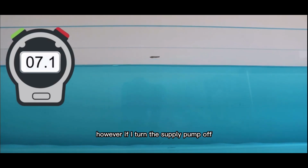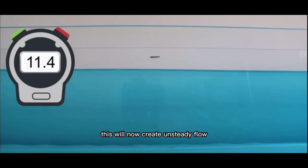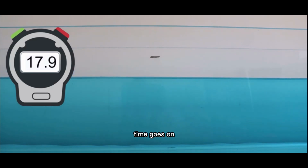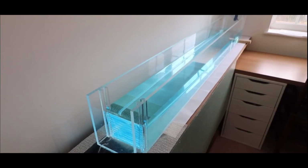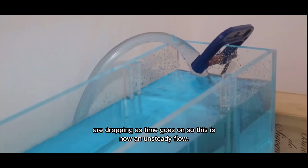However, if I turn the supply pump off, this will now create unsteady flow, as the discharge, velocity and area will now change as time goes on. Here we can clearly see that the depth and therefore the cross-sectional area are dropping as time goes on. So this is now an unsteady flow.